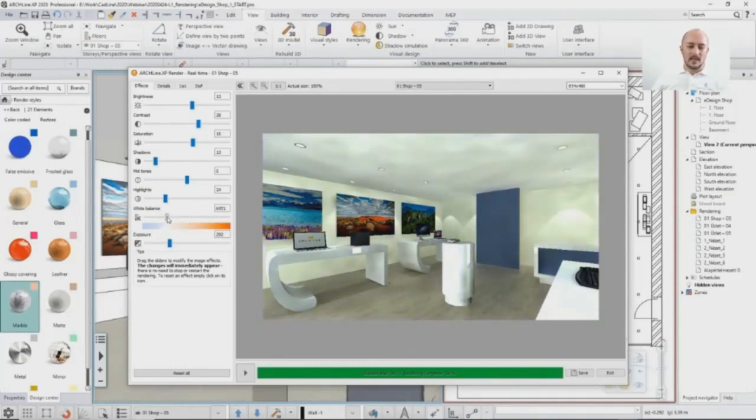The white balance is for a mood effect as well, because if you use a cool white balance, cold colors, then you can set up a feeling for the same render. I didn't change the sunlight outside, but I can set up a scene looking like it is, for example, somewhere in Sweden in wintertime, or I can just dial this up and bring in more orange, and in that case it looks like somewhere in the Bahamas or somewhere else.